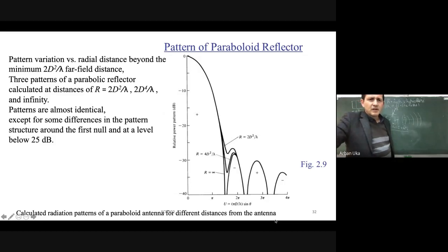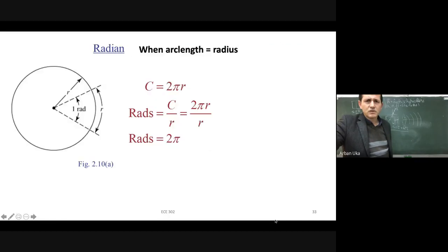Now here we can see again the power distribution as a function of the angle. As I think we talked about before, the power can even get equal to 0 at the first null beam width, but we don't have only the first null beam width, we have also other directions which are equal to 0. And here we see a picture of the power distribution. We are going to solve examples regarding the power distributions very soon.